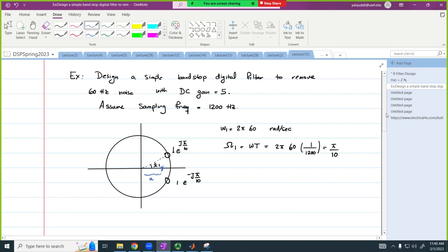Therefore, I'm not concerned about what happens here and here, and therefore this might work. So really, the exact shape will depend. If it is just an interfering signal, and around that band there's no good signal that I'm trying to keep, then if there is a little attenuation, it doesn't matter to me. If not, I just want to remove this one, and I don't want to impact any other because the signal has some components here that I want to keep, then I will use a notch filter because it's going to be much sharper.